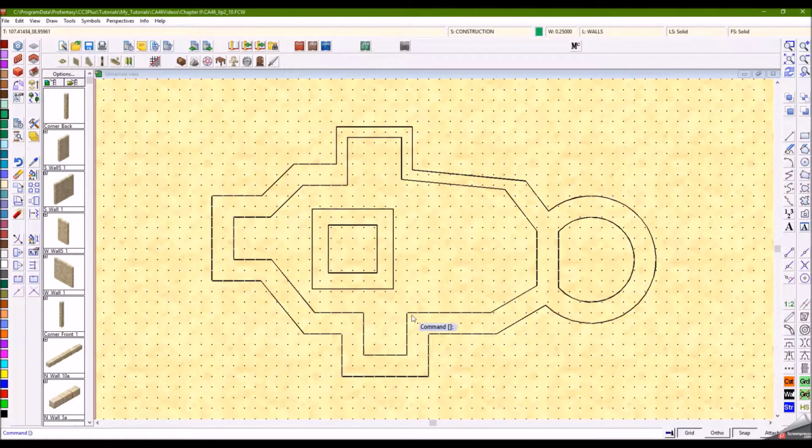Here there is a lodging or stable or whatever that is perpendicular to this wall, and we start from this endpoint with a line and the endpoint modifier. We want it to be perpendicular to this line, so we use the perpendicular tool. And now we are asked for a distance. The distance can be positive in a way and negative in the other. So what is the right one? I selected the line to be perpendicular to here.